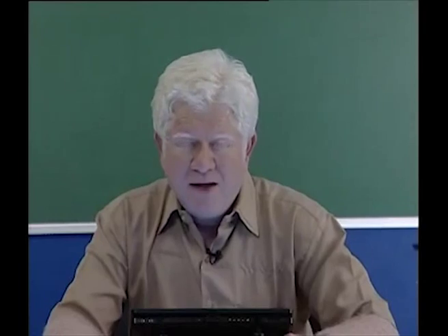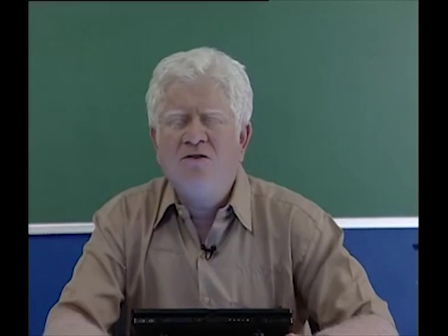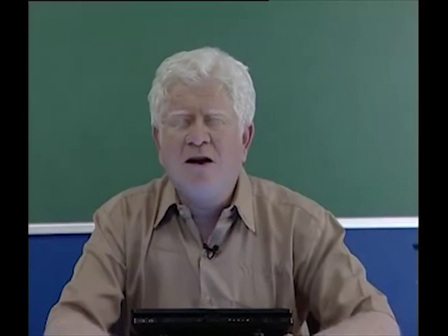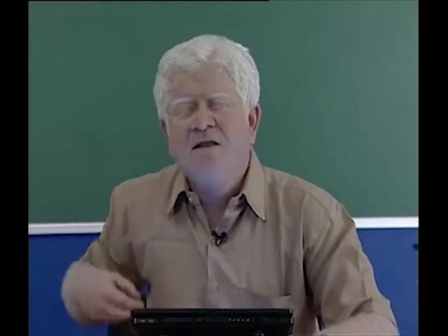For the continuous time case, however, there is a practical problem that arises, and that practical problem is simply that whenever you differentiate a continuous time signal which is corrupted even slightly by noise, then the noise tends to get amplified under differentiation. So, repeated differentiation of a signal can be suicidal. It increases the noise level in the signal to greater and greater extents and reduces the performance of the entire differential equation solving system.